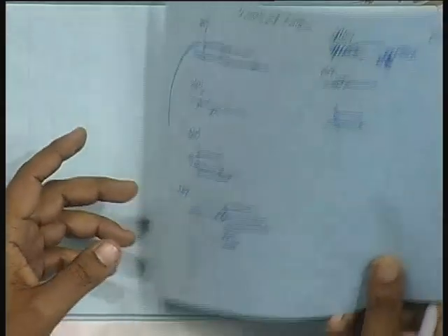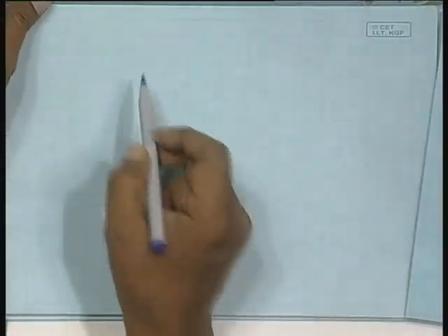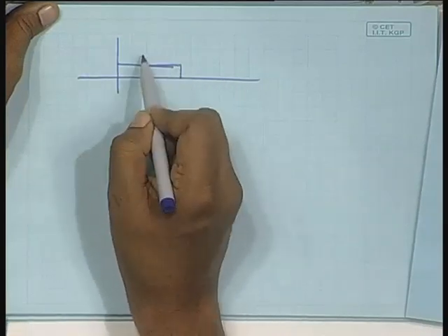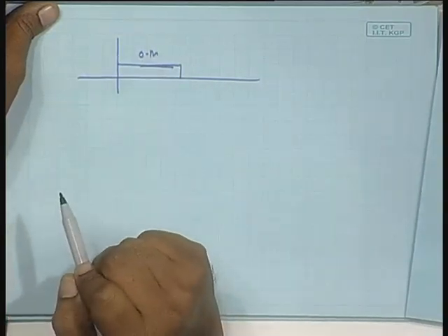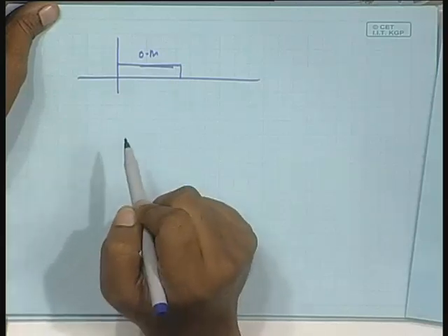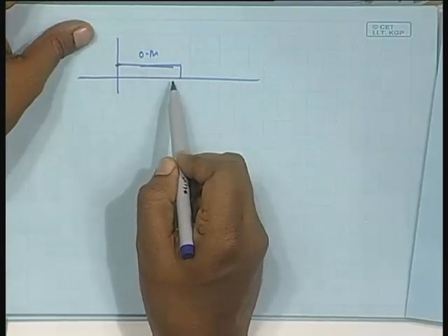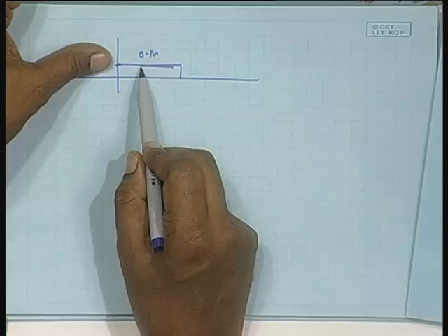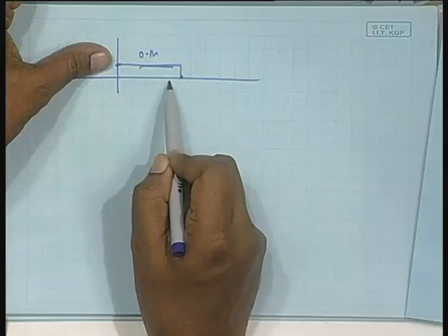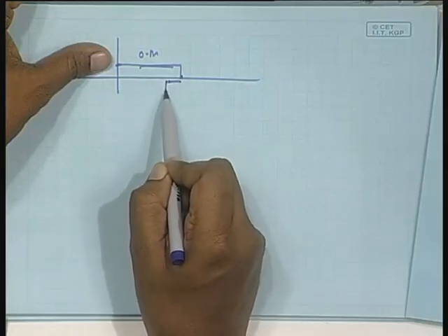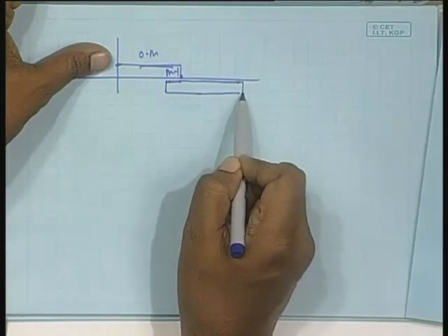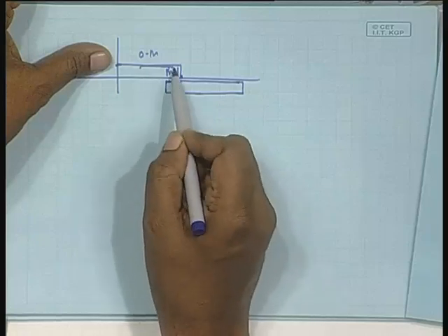Now, I propose a technique to carry out this long convolution, that suppose I break this data like this, I will have an overlap. This is my 0th block, next block, in the case of block adaptive filter, this will be that block, by the way. Next block, instead of starting here, I come back, how many points inside? M minus 1 points inside, and go like this. That is, here I have overlap.